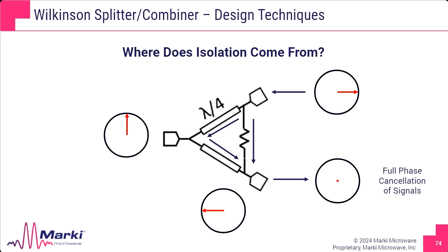And the 180-degree phase rotation is what provides the isolation. As you move above or below the frequency that this was designed for, this null in isolation begins to creep up. And we'll actually see this in one of our simulations. The isolation begins to creep up as you leave this frequency that it was designed for. And that makes perfect sense because these transmission lines are a quarter wave at a given frequency.